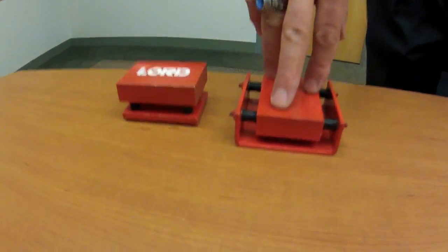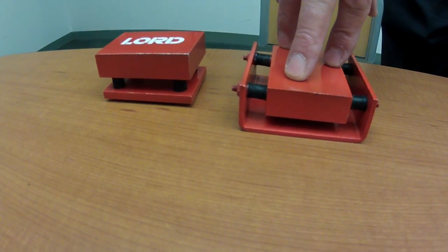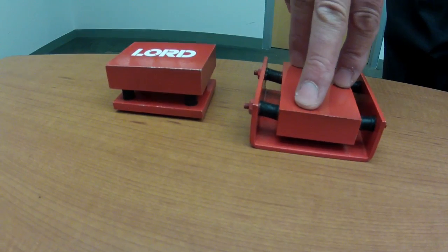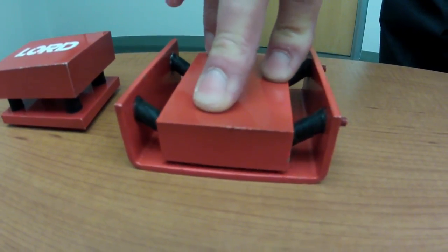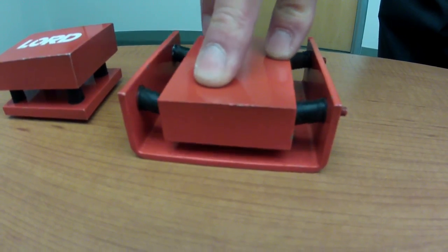This is a demonstration of shear and compression mounts. The sandwich mounts shown in the two demos are installed in shear. These are the same mounts, just installed in different orientations as we described in the seminar. This is a shear mount where you can see we have quite a bit of deflection capability in the mount that isolates the package when you have a given shock input.